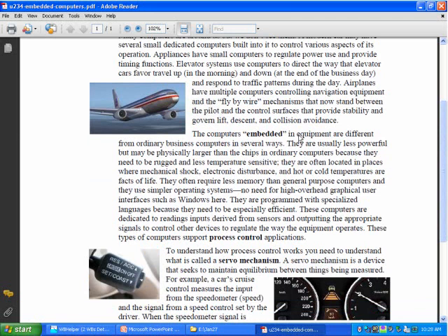What happens in the fly-by-wire environment is that, think about an aircraft that is called hypercritical. It's designed to be very high performance, like a fighter jet. It's going to be going very fast. It's going to have wing surfaces that are very critical in terms of their adjustment, and a pilot may not even be able to control it adequately because the human reaction time is too slow to control this.